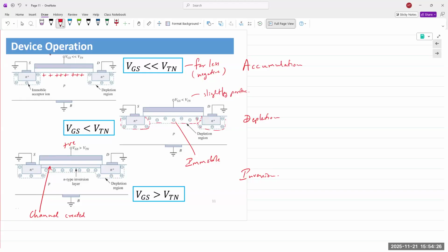Those electrons would flow out of the gate, except there's an insulating material, so it stops right there and creates a shallow layer of n-type material. That channel now connects both the n-type regions on either side. And that's why the overlap is important. If this did not exist, then there would be a break in the channel, and the channel would not connect to both ends. Does that make sense?